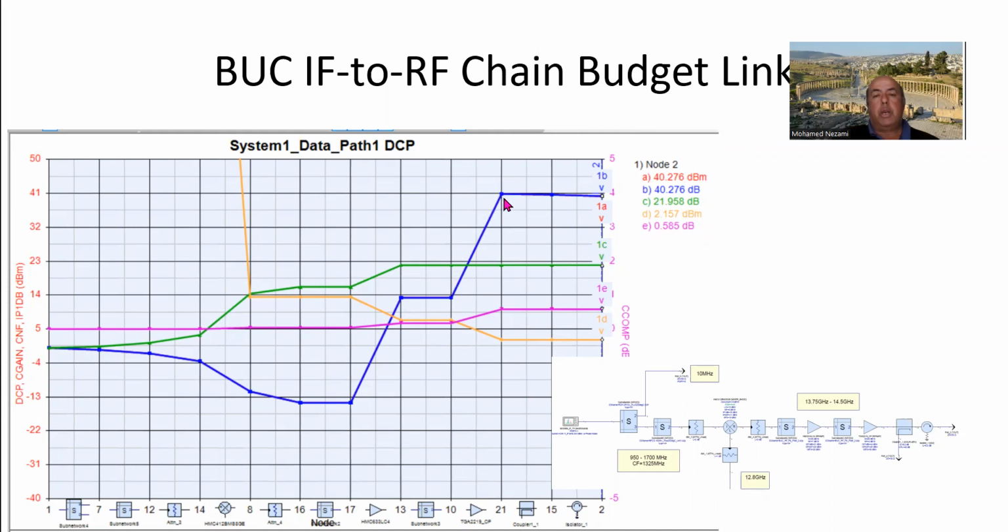We have the large signal gain in here, and then we have a tiny little loss from both the directional coupler and the isolator, and these are estimated at about 0.6 dB. Now, if you trace the other parameters, they're all the same way. So basically, one thing good to monitor is this compression in here.